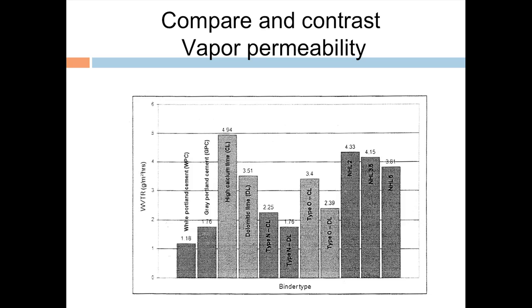But it's also the sacrificial part of a masonry wall. It's much easier to replace mortar than it is a brick. It's much easier to replace mortar than it is a stone, especially if it has some type of significance, if it's carved and a lot of time was put into its manufacture. So when there's moisture in a wall, it needs to go somewhere. It's supposed to go through a mortar joint, not necessarily through the brick. I'm sure if you walk around any town or city, you can see where cement has been put over top of a lime mortar joint, and the brick falls apart, deteriorates, and traps the moisture.